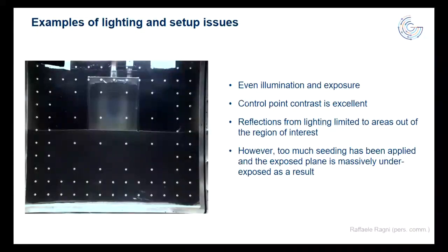But what is a big problem is he's used too much seeding. So this sand ordinarily is just silica sand. It would be a light brown color. He's decided he's going to put some dyed black sand into that mix. And in this case, he's put too much in. The reason that happened was he was doing this experiment with a pore fluid called methocel. And oddly, when we back saturate the sample with methocel, what looked like a really nicely textured sample in dry sand just turned into this black mess.